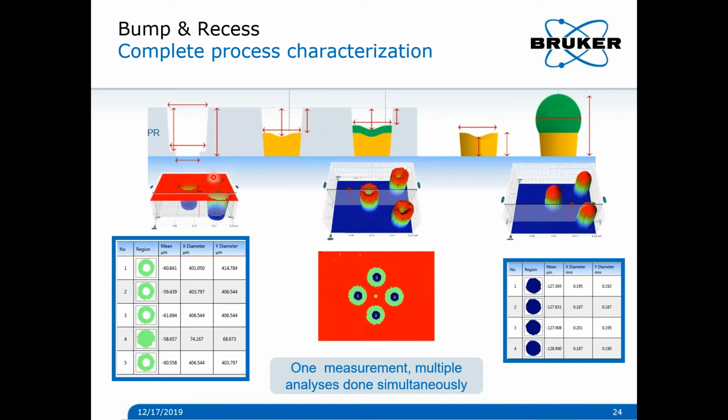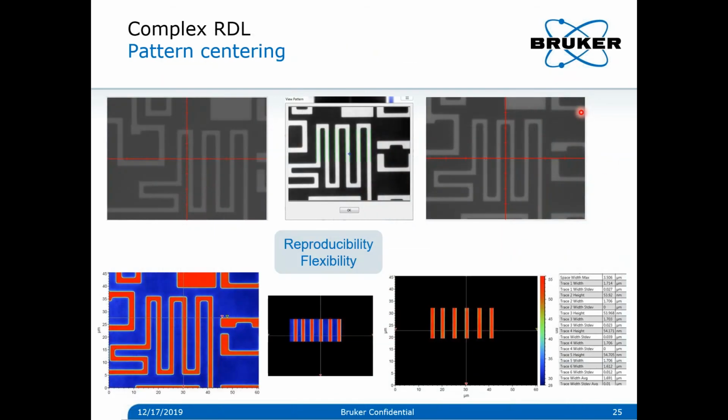So if there are any missing bumps, we will flag this by the number of bumps detected, or if there are any deviations over a certain width or height, we will also spot that in an absolute manner. So along a die with very high density bumps, we can tell the absolute coordinates of that bump versus the origin of the die, and tell where maybe we can send some repair tool to reflow the ball, for instance.